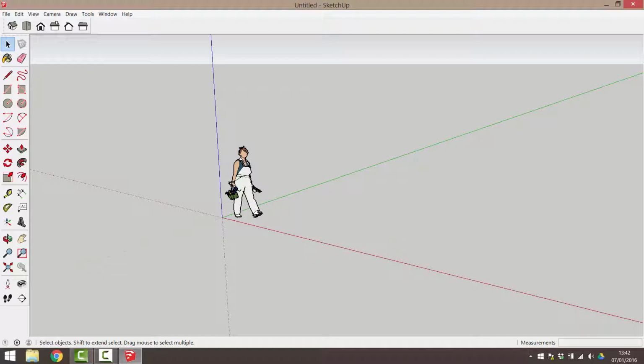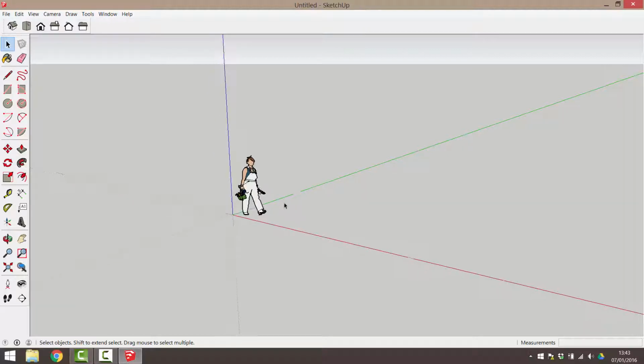The person standing in the drawing area has been included in this new drawing to give scale and perspective. She is drawn at a scale of 1:1 and has been placed at the point of origin where the X, Y, and Z axes meet. This immediately gives a 3D feel to the drawing area. If necessary, you can remove this person by clicking on them using the black select arrow and pressing Delete on your keyboard. For the purpose of this tutorial, we'll leave the person on screen. The last of the 3 elements mentioned is the horizon. The existence of this horizon helps to orientate you.